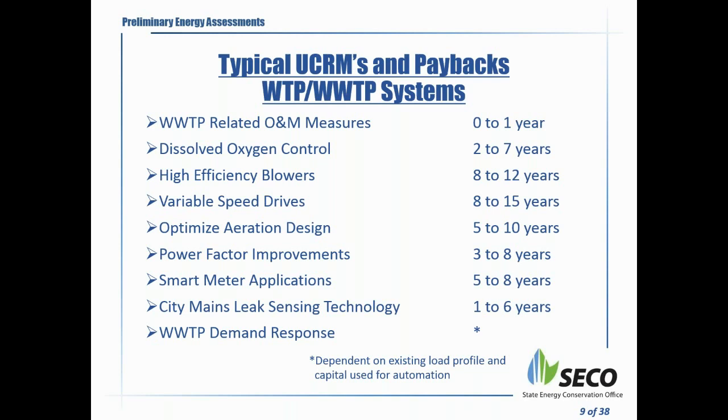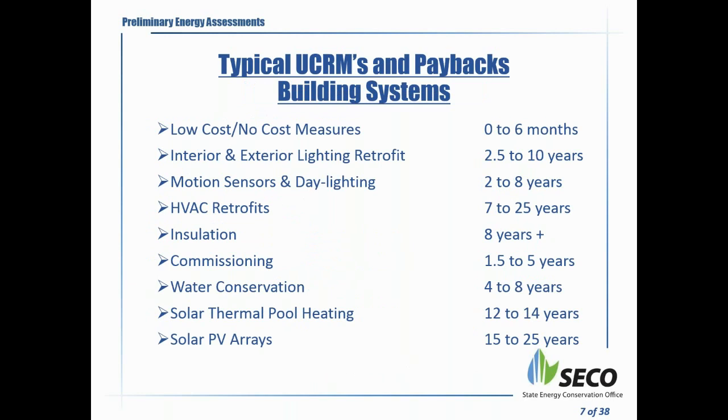So the question that is often asked, and I'm going to go quickly back to the building side, is: okay, why, for a lighting project, I thought my payback would be 2.5 years, and you're telling me about a 5 or 6 year payback? The most important thing to keep in mind is that the payback is contingent upon how many hours of operation you use that facility, and what the cost of doing that project is. They could vary from one location to another, from one site to the next, depending on the conditions at the site and the bidding environment.